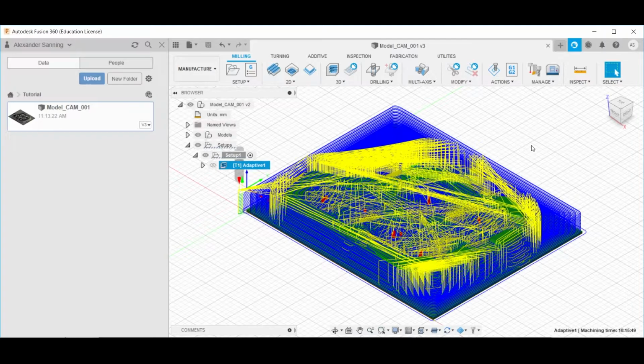An example of this is that having used a very large 16mm ball end mill to remove as much material as possible, we now use a flat end mill to remove the scallops left from the ball end mill of the clearance toolpath and come as close as possible to the actual model while still leaving a sufficient margin for the final toolpath to define the actual surface.